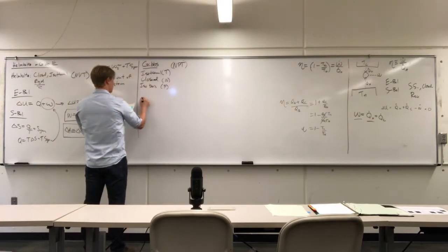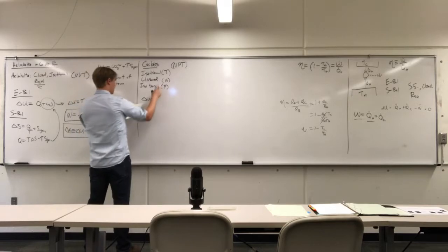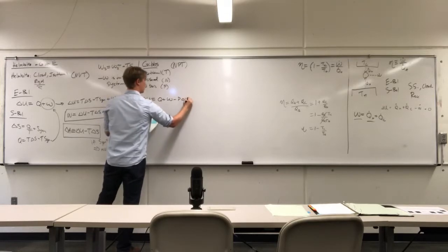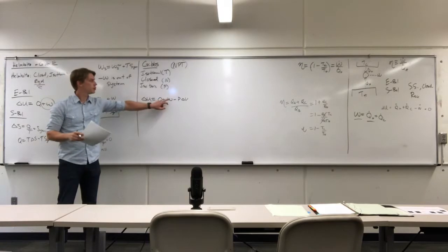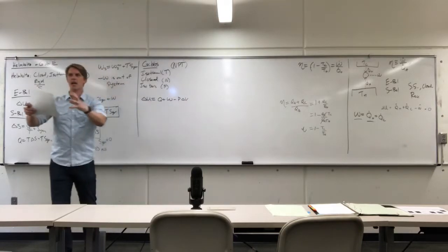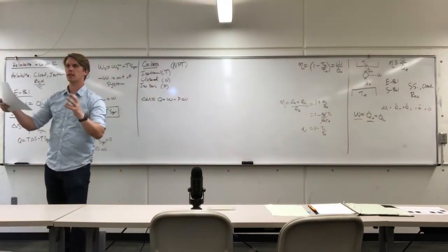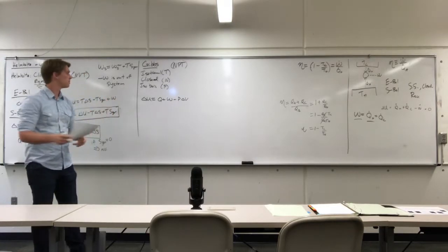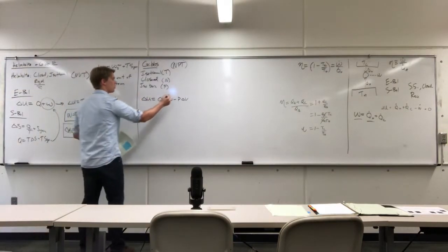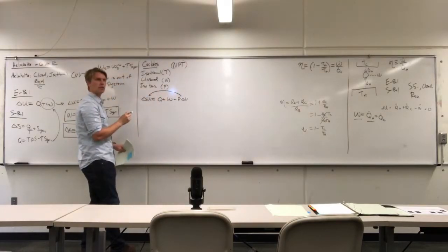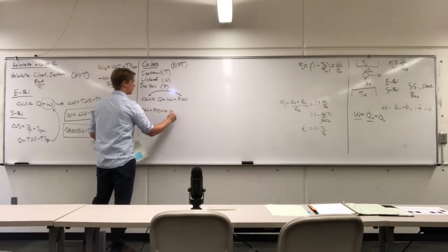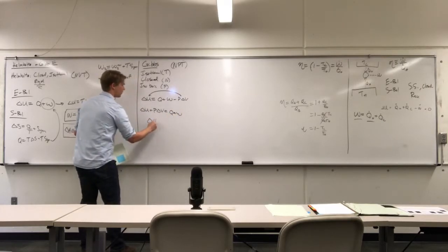So if you write out our energy balance, in this case, the change in internal energy of our system, heat, shaft work, so this would be our turbine, PV work, this is the entire unit operation, expanding and contracting, pushing back the atmosphere. So the only difference between the Helmholtz derivation and the Gibbs derivation is that we take this term here, move it to the left-hand side, change in internal energy plus pressure volume. This is the definition of enthalpy.